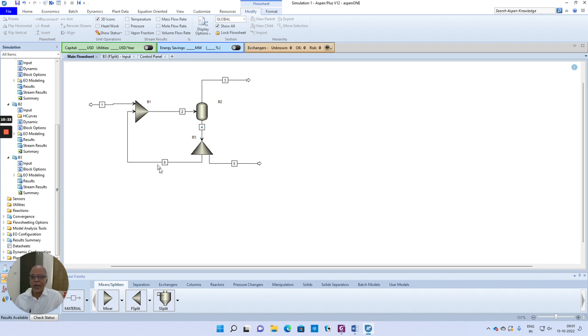To start with, we did not have any idea about this recycling. So, how is it possible to solve this model to calculate stream 2? Whenever you have a recycle in the sequential modular approach, the recycle is automatically taken as the tear stream. Tear is nothing but a guess. So the simulator will be making guesses for this particular stream. What do you mean by guessing a particular stream? At least you are required to guess variables equal to the number of components plus 2, so that you will be in a position to calculate any property with respect to that stream. In other words, you must be able to satisfy the degrees of freedom for that stream, which we have already seen as C plus 2.